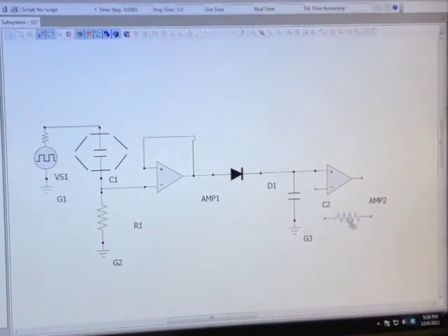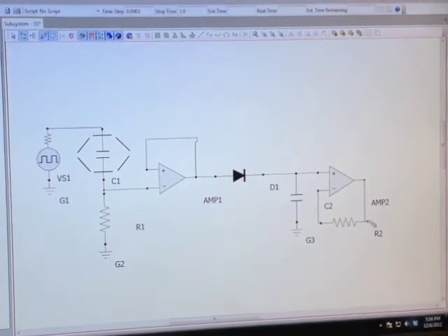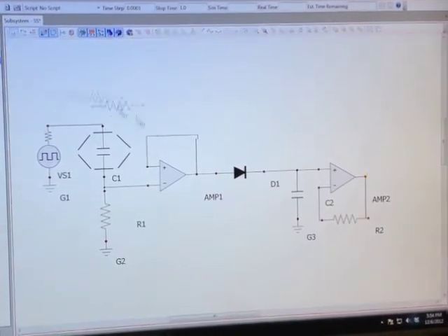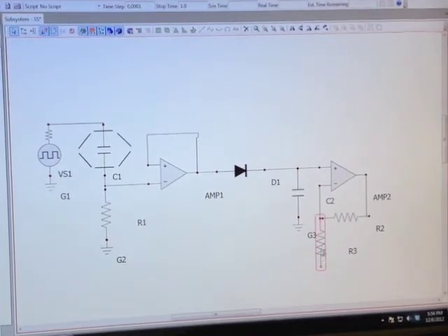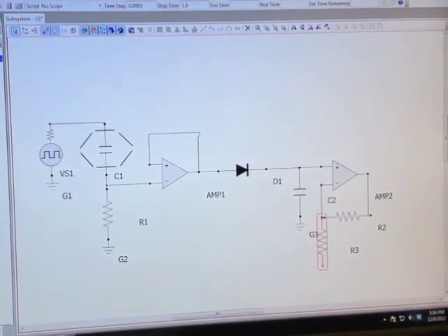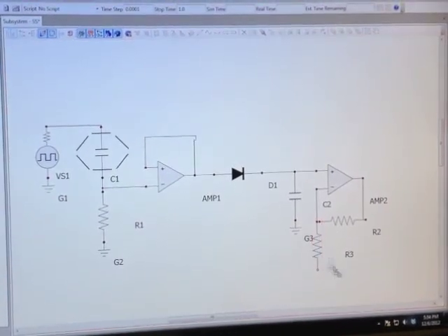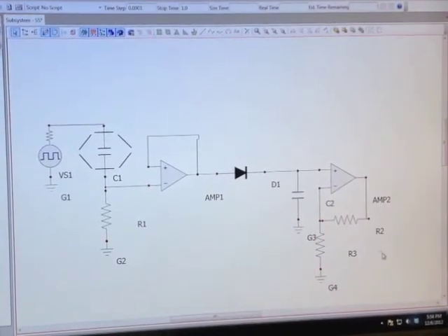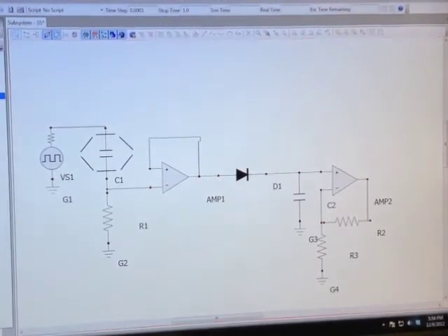The total capacitance of the parallel plates is very small. Its value is around 0.06 nanofarads in air and around 0.17 nanofarads in water. In the circuit we built, without the use of an op-amp, the change in capacitance would cause a change in voltage that is too small to detect. However, we included an op-amp to amplify the output signal.